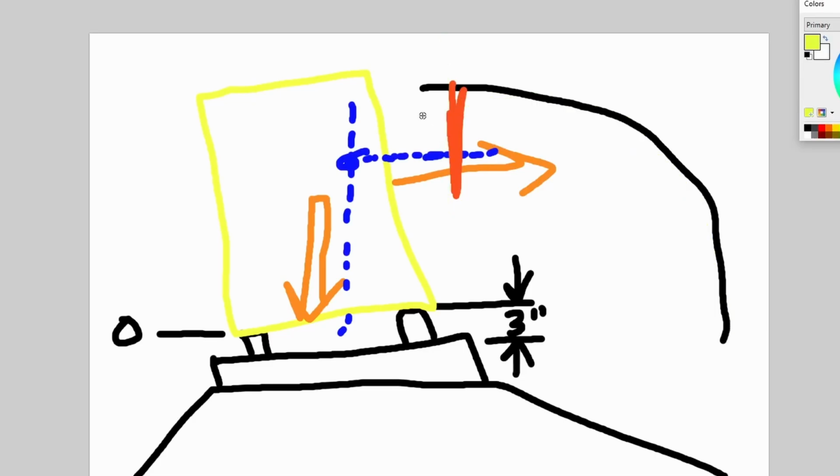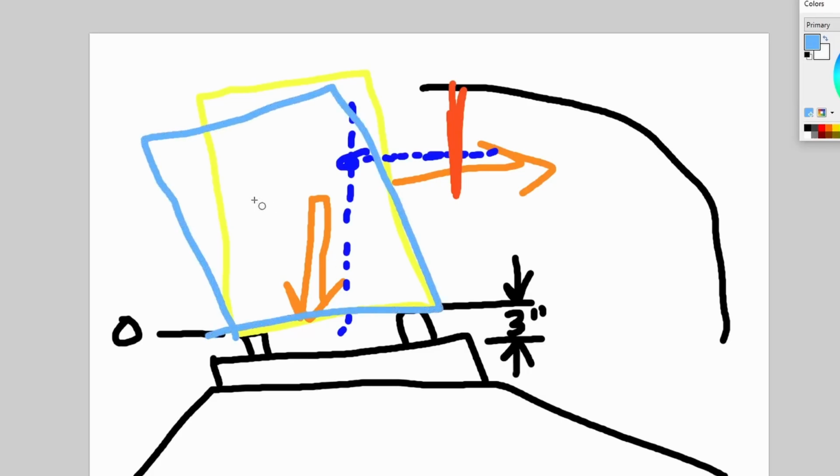And one nifty thing is some really advanced high-speed trains, particularly in Europe, but some here in the States, will actually tilt. They have tilt technology, like the Talgo trains that Amtrak has, where they can take their normal train and adjust the suspension with some control and shift it so it tilts inwards so that it applies its own elevation as well, which further moves that inwards. And so that way they can run faster around the same curves as our conventional trains. And so that's what superelevation is all about.